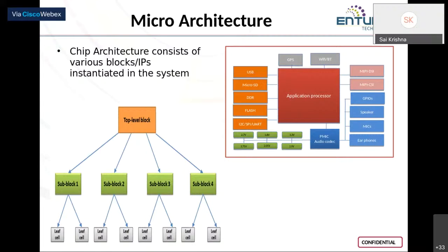We first break it down into pieces, subblocks, and then each subblock is taken through the complete ASIC design flow first. So for this subblock 1, what is the specification? How do you write its RTL code? How do you verify it, and then perform synthesis, then timing analysis, then DFT, and then physical design, physical verification, and then only when everything is qualified, you take that subblock design and integrate it back into your chip level design. So that means here you're talking about two different hierarchies. One is at your chip level or your top level block, and the other one is your subblock. Okay, next.